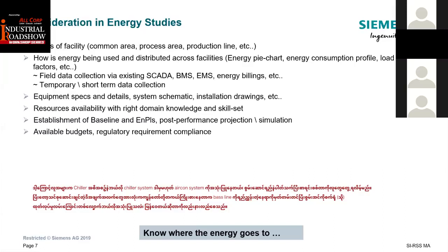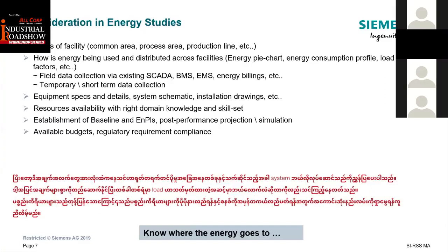With all this information that you collect, what we are trying to establish is the baseline, the point of reference, and to understand how energy is being used and distributed across the facility or the production line. From this data, it also gives us an indication of how the system performs under certain loading conditions, and that's why I establish the load factors. We also look at how the equipment reacts when the load is at a certain level. This study helps us understand the equipment better and find the best way to operate the system.